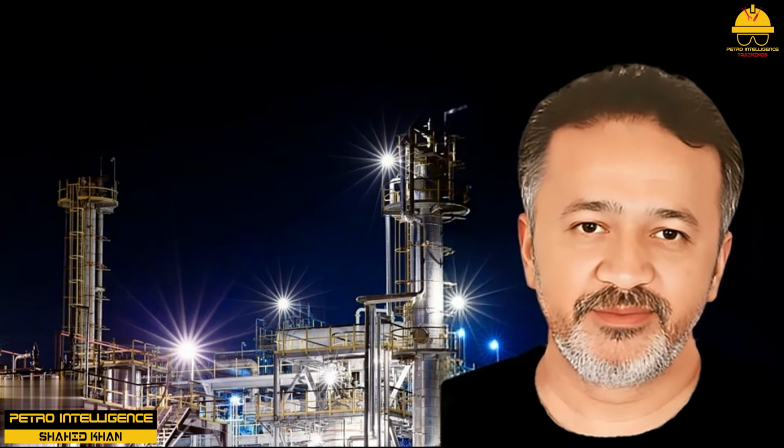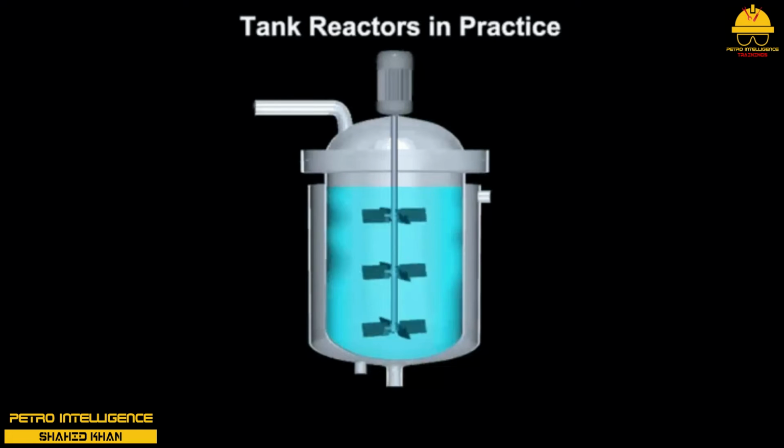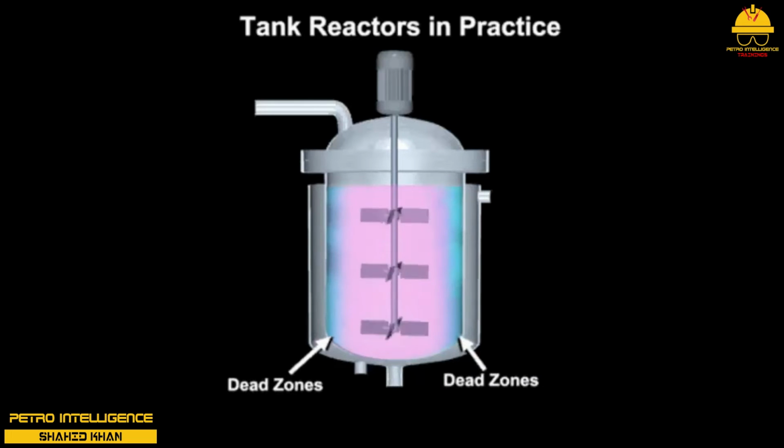Stirred reactors. A common type of reactor is the mixing or stirred reactor. The basic components of this device will include a mixer or agitator mounted to a tank. The mixer will have a direct or an indirect drive. The reactor shell is designed to be heated or cooled and withstands operational pressures, temperatures, and flow rates. The design may include tubing coils wrapped around the vessel, internal or external heat transfer plates, or jacketed vessels. Hot oil, steam, or cooling water may be the heating or cooling medium.